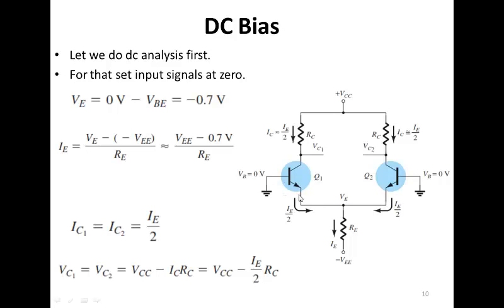If the transistor is in the active region, then there would be IB flowing in the transistor, there would be emitter current, and there would be a collector current in this transistor and this transistor as well. To compute the emitter currents and collector currents, first you see that the base emitter voltage is 0.7 volts, the voltage between these two terminals is 0.7.